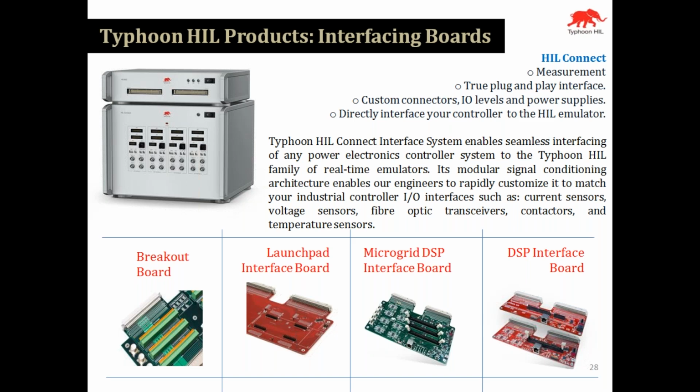Typhoon HIL emulates the power stage of a power electronic device, including power converters, electrical machinery, filters, electrical grid, PV panels, passive elements, etc., with 1 microsecond overall time resolution. In this way, the user can develop and immediately test their control applications without worrying about the safety measures required in the power laboratory environment. So this is the purpose of using the Launchpad and DSP interface board.